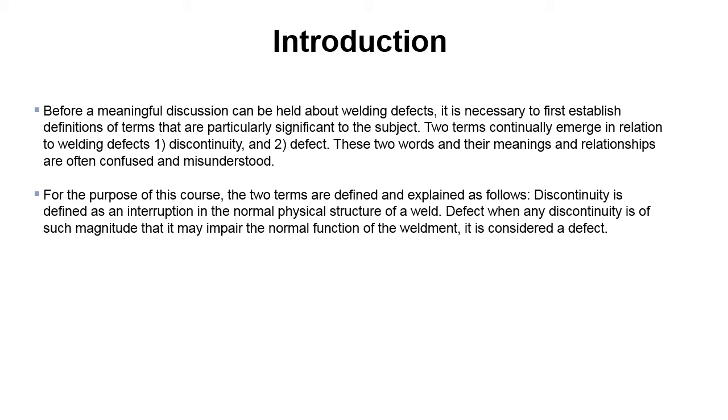And in this case, you need to look at the codes, the specification, and your inspection criteria to see if the discontinuity is a defect. So that's the driving force. What documentation are you working to? Is it a defect or is it a discontinuity? You need to look at the rule book and see what game you're playing.